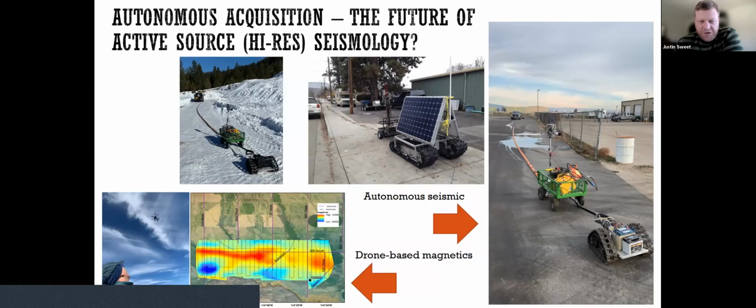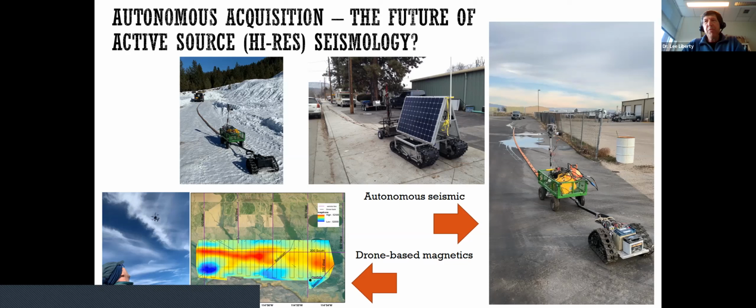I wonder, Lee, if you could say a little bit about the shallow active seismic work here. You mentioned that the kinds of tools you've talked about maybe wouldn't be as appropriate for your surface geophysics application. But typically, what kind of depths are you looking at, in terms of the range of depths from which you're getting usable data back with some of these land streamer deployments? For the tomograms, both VP and VS, we're seeing typically down tens of meters, and for the reflection images, we're seeing down hundreds of meters.